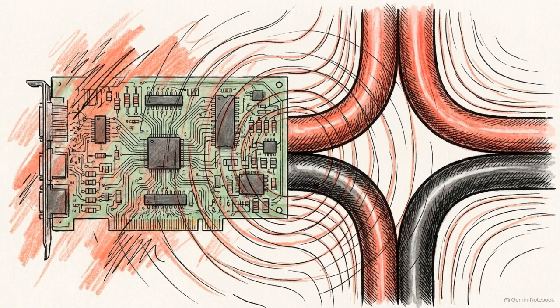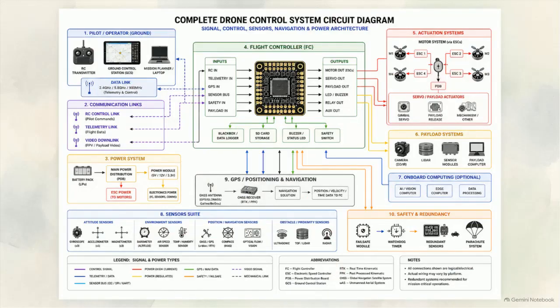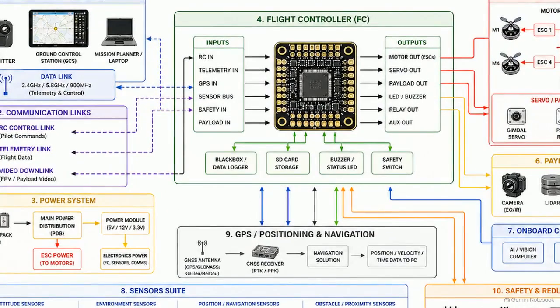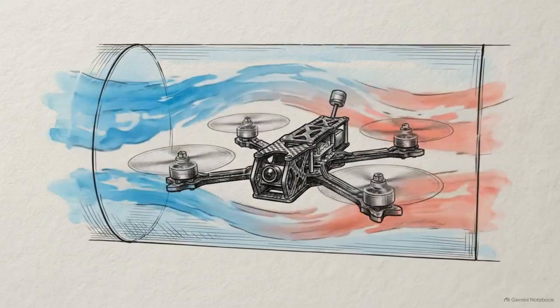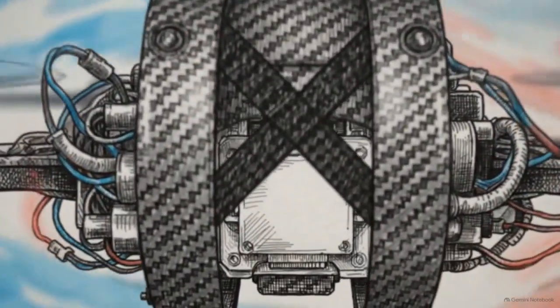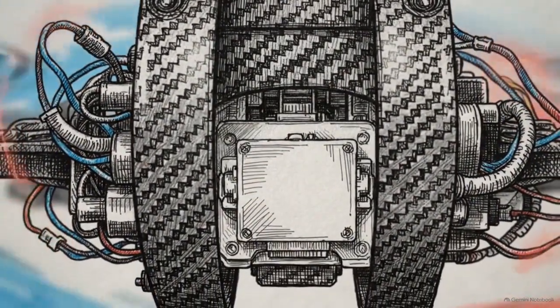High current power creates massive electromagnetic interference. If that interference reaches the logic circuits, it can corrupt the telemetry. The architecture solves this via modular separation. Thick red lines route high current power from the distribution board directly to the ESCs, isolating massive loads. This contrasts with thin, yellow pathways delivering regulated power to sensitive electronics inside the flight controller. Strict physical and electrical isolation between logic circuits and power distribution is mandatory to prevent electrical noise from crashing the aircraft.